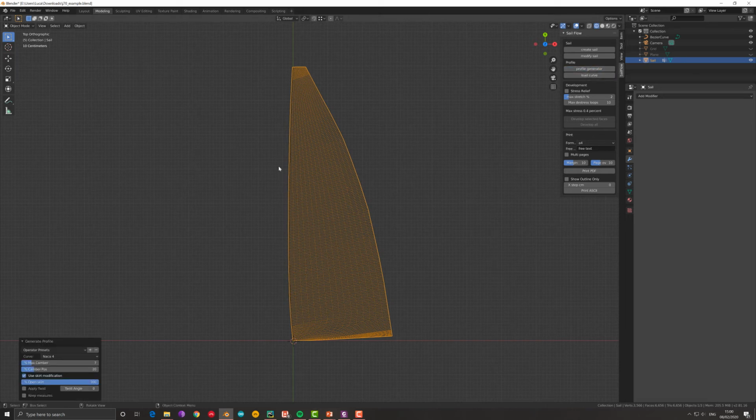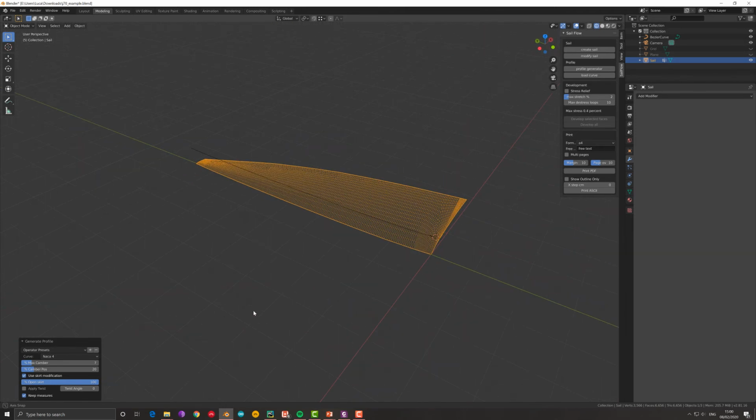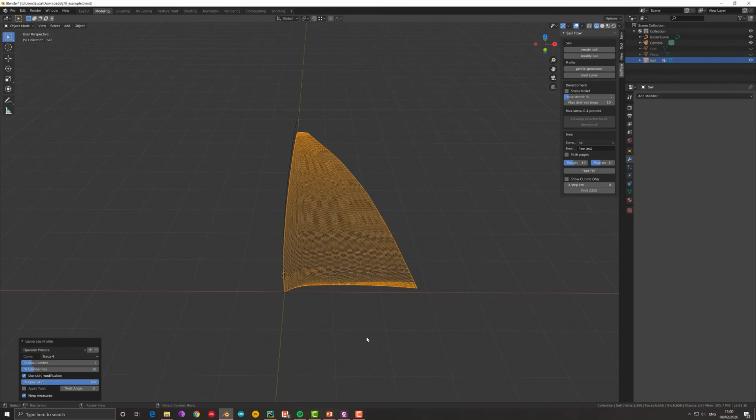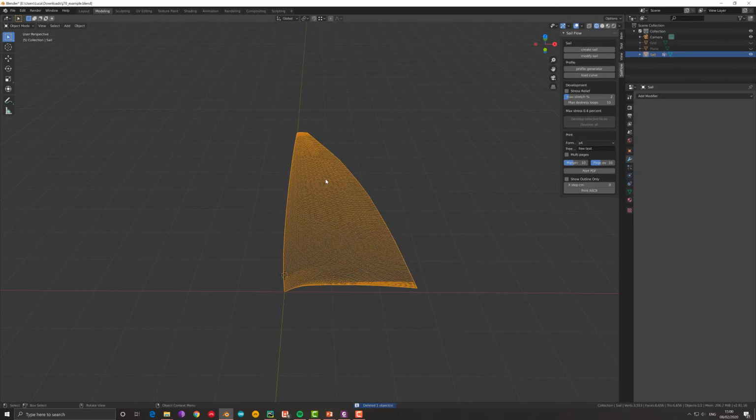Voila, and now our sail is curved the way we wanted and is subdivided in a mesh the way we wanted. We go back to SailFlow tools, we go to profile generation, and we apply the number we want. And we also press keep measure. In this way, the sail, when it's flattened, will stay within the measure of the standard. Let's have a look how it is with a camber of 7 and a position of the camber at 20%. I think it looks okay.